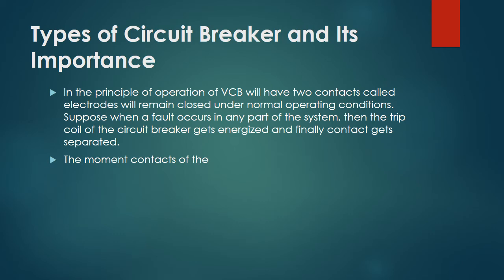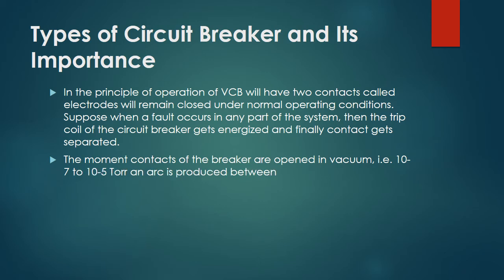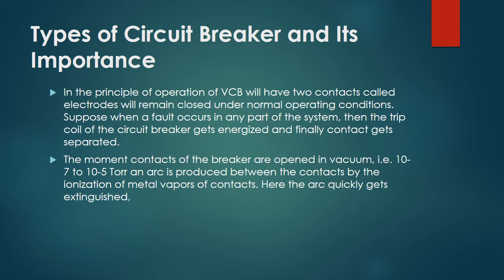Advantages. VCBs are reliable, compact, and long life. They can interrupt any fault current. There will be no fire hazards. No noise is produced. It has higher dielectric strength. It requires less power for control operation.